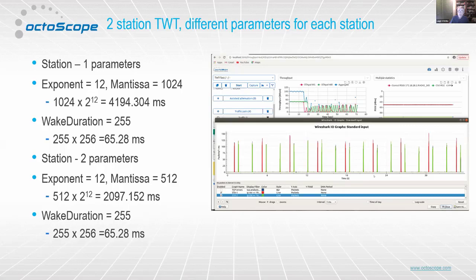I see something coming up here in the chat: TWT is more efficient in 6G than in 5G. I guess you're talking about 6 gigahertz and 5 gigahertz, and it's a question, since the AP services only 11ax clients and does not have to worry about legacy power save. Yeah, I think that's probably true in some sense. If everyone is supporting TWT and you don't have devices that are essentially not able to be scheduled, then yes, I imagine the whole system would be somewhat more efficient.